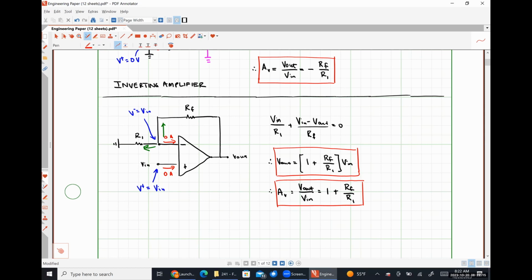So if you had a piezoelectric sensor that you were using to, say, measure vibrations or something like that, because you're just going to be measuring some sort of mechanical deformation of this thing, you would need to run the output of that sensor through a unity gain buffer in order to allow the power supply to add current to your system so that you could use that sensor's output to actually drive some sort of load. So a unity gain buffer, even though it literally just has a gain of 1, is a fundamentally necessary op amp application.